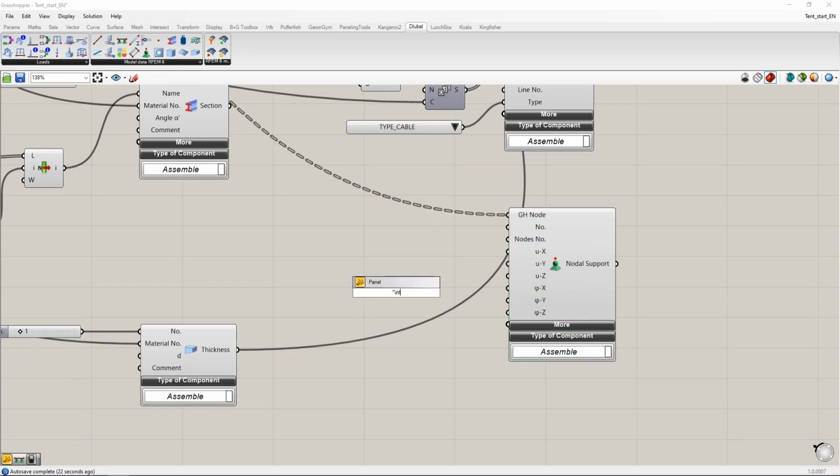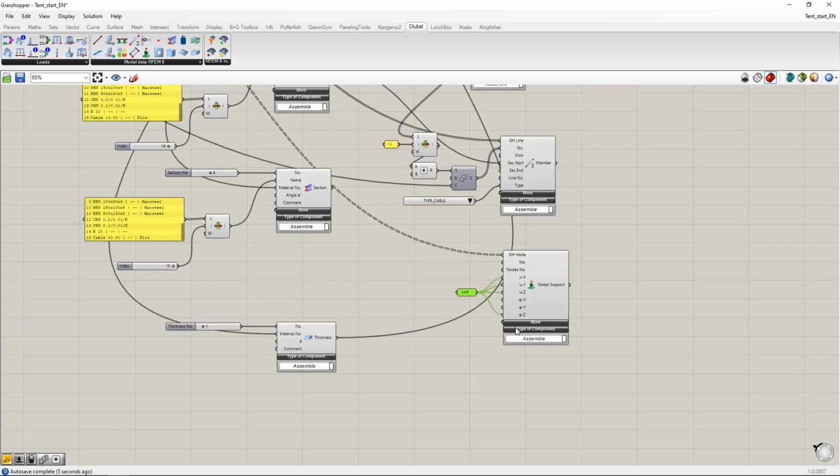Regarding the definition of the nodal support, where is it written? Yeah, it's written here also in this small info box. In case a support is free in a certain direction, you would enter the value 0. In case it is fixed, so it could not move in this direction, you use the string INF for infinity. And anything else is a value in Newton per meter. So I will fix my supports in specific directions and also the rotation about this global Z axis. Okay, so this is fine.